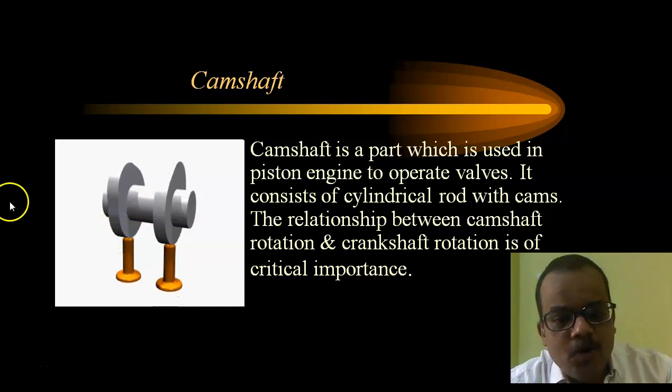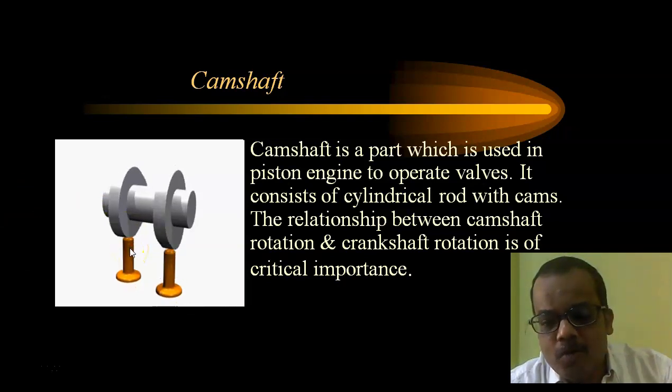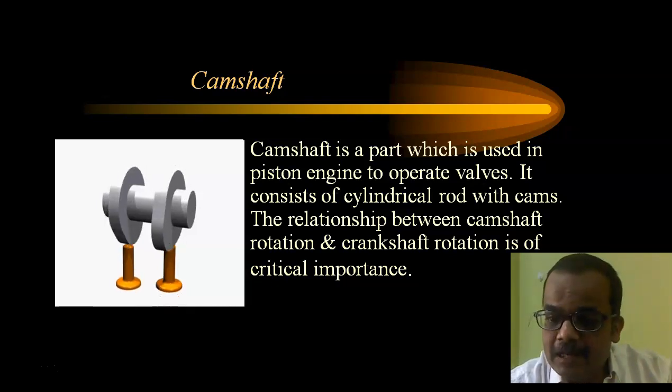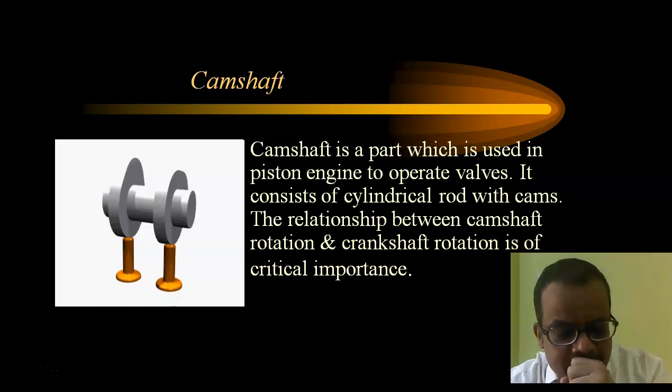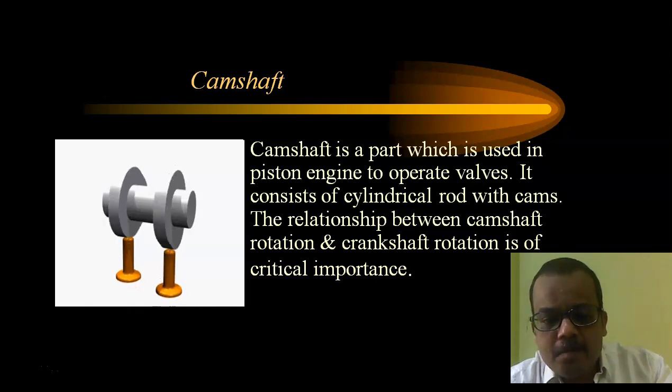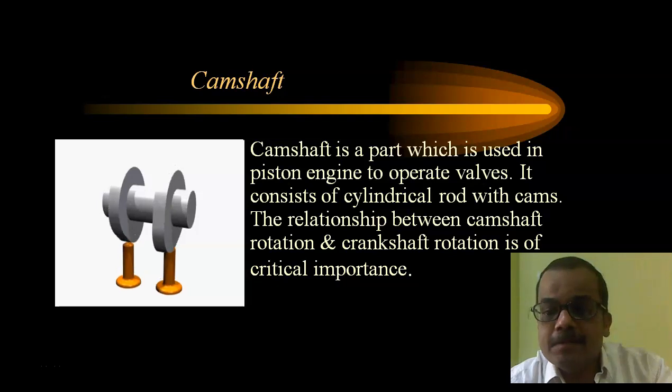When a particular cam lobe comes under this rod, the valve gets opened or closed. A particular timing is given to the engine, and that timing is very important, because if there is a problem in the timing of an engine, there will be a great loss of efficiency. So you have to see that it has proper timing. The function of the camshaft is the opening and closing of the valves.